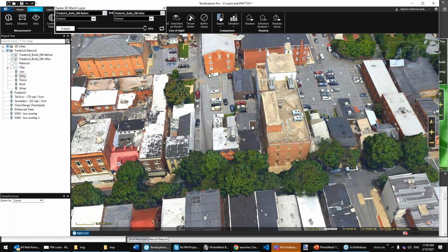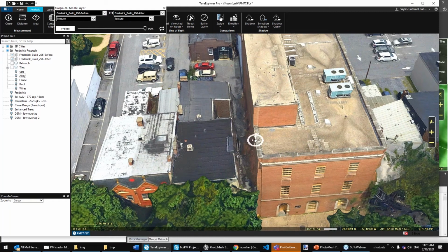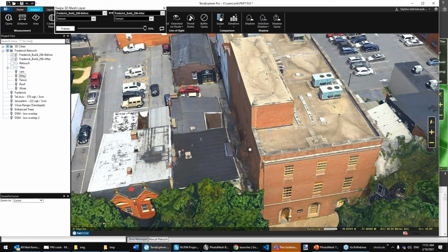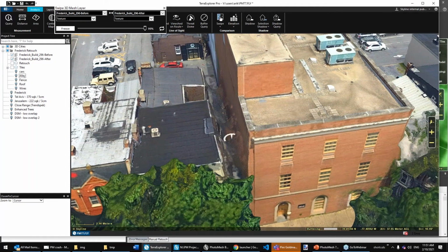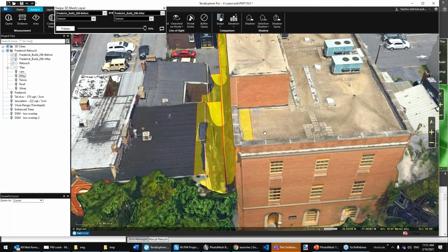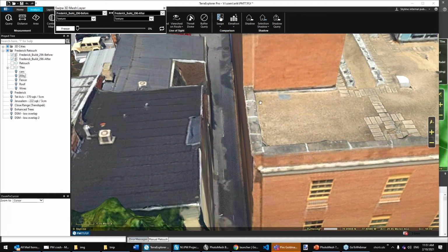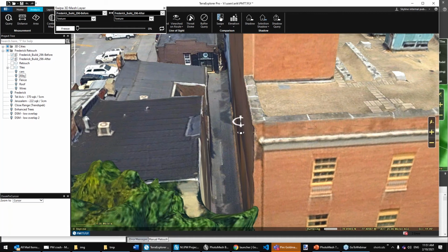So this is a problem of a very narrow alley, and PhotoMesh didn't have enough overlap to understand the geometry of the gap between these two buildings. That's a common problem if you have very close by or nearby buildings. And adding the manual retouch object, in this case I added two, one for the right building and another one for the left building, and I'll turn it off, and that's again the before, and that's the after, and you see that the alley is very sharp, very clean.